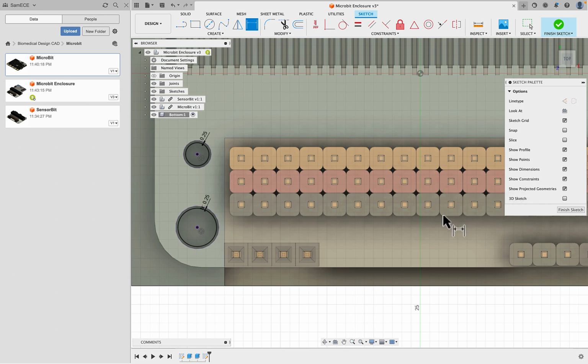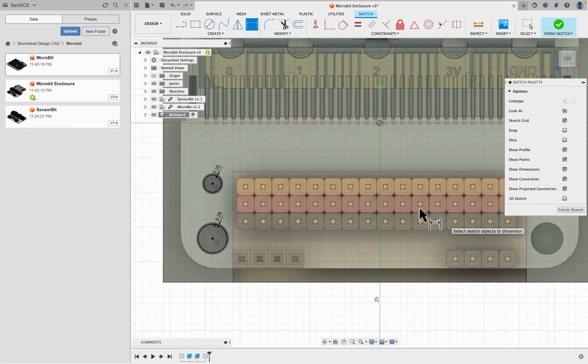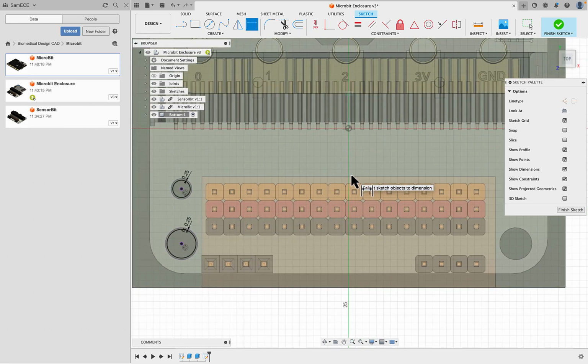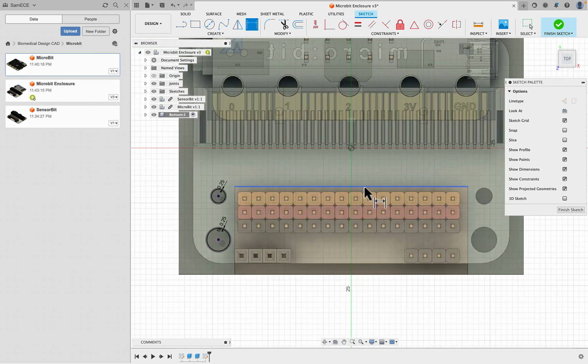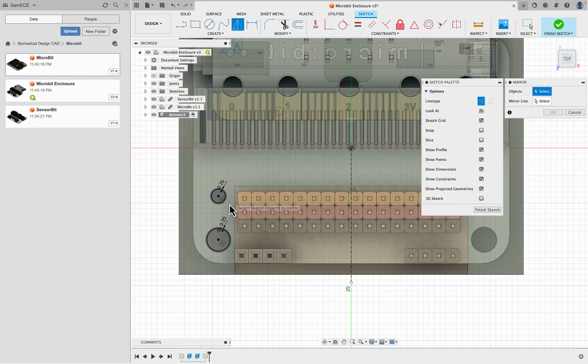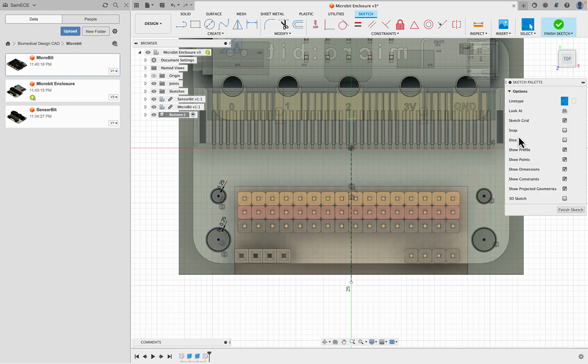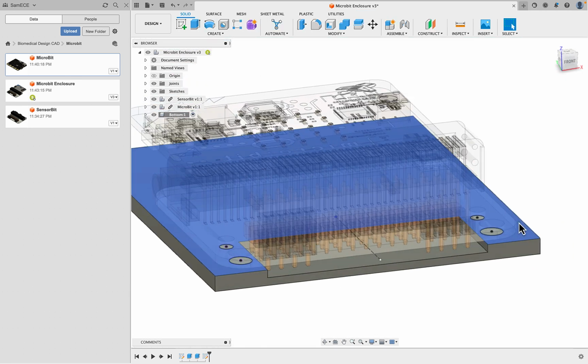So next up, we would mirror these two circles to the other side. So I'll just hit L and create a construction line from the origin down to the bottom somewhere. Doesn't really matter, just a vertical line. And then I'll do the create mirror, and I'll get the two inner circles mirrored about this mirror line. So now I've got all four circles, which is what I wanted, so I hit finish,